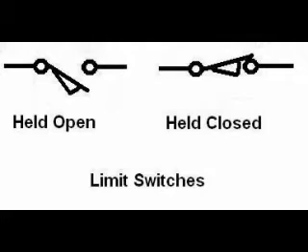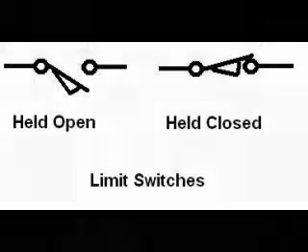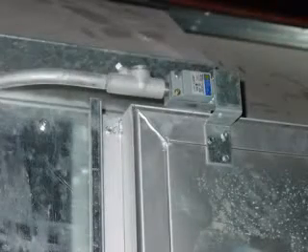The symbol on the left is of a limit switch held open by a spring. It must be actuated to close. The symbol on the right is of a limit switch held closed by a spring. It must be actuated to open. Here is a limit switch used on a door.